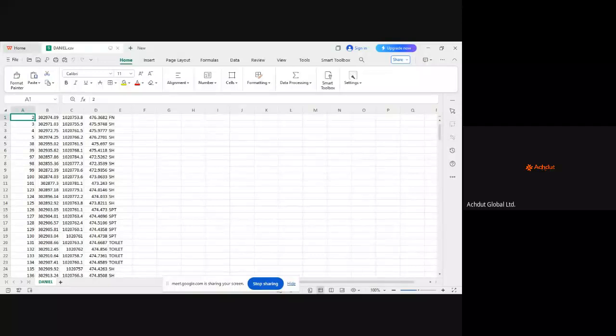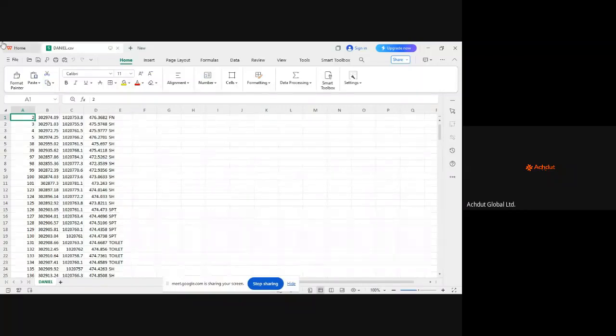That is why you have spot heights. They are just random numbers that you pick, sometimes at 10 meter intervals, at 5 meter intervals, at 20 meter intervals, depending on the accuracy you want to achieve from the job you're doing.